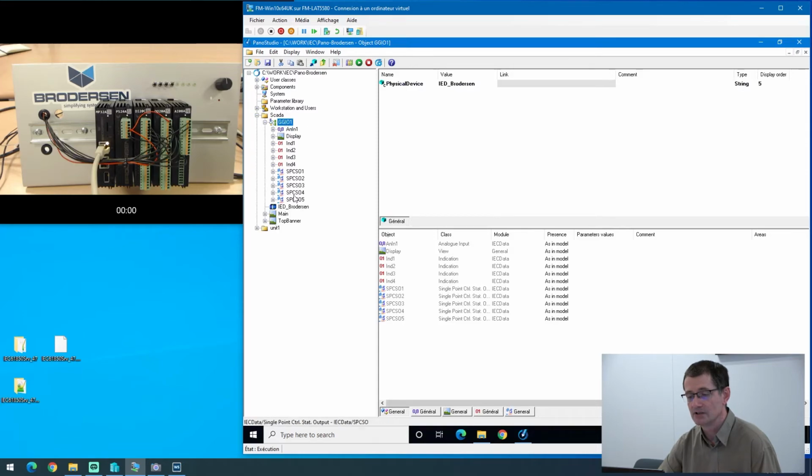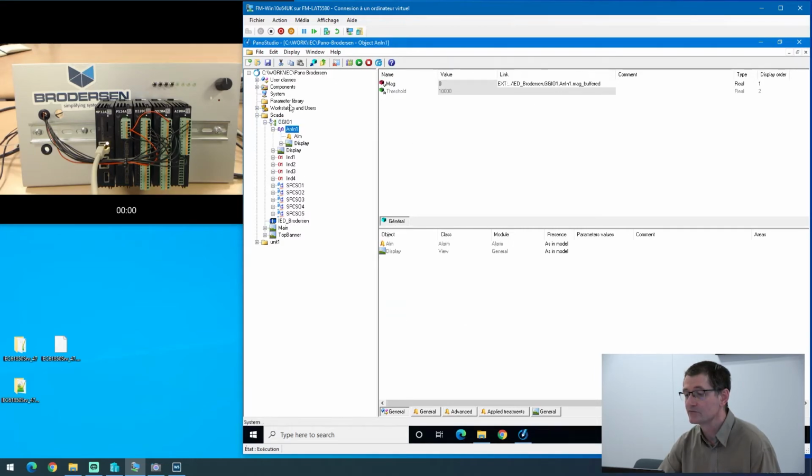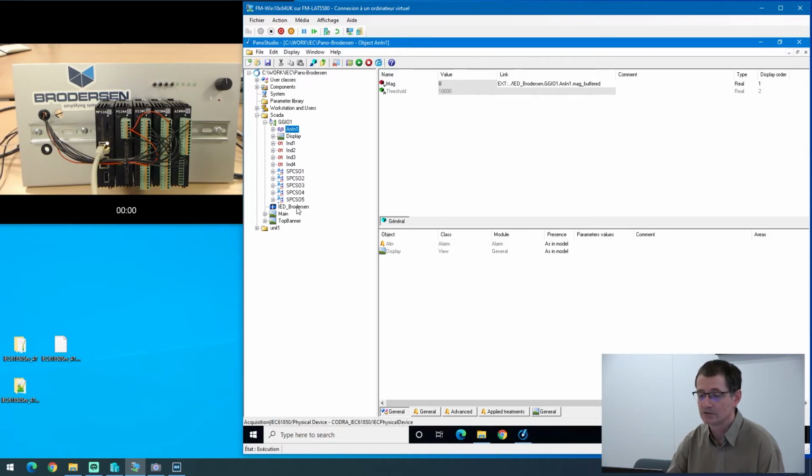And you can use this object as a source for external links, which means that you can then create components that can build the links from the structure of the components and maybe work in a more traditional way for Panorama, and especially a way where your components will already embed whatever treatment, like alarming or display, that you want to do with the information. And so here, when you work this way, it means you don't have a big connector and the component. You just have the component, and the component builds the acquisition configuration, these external links, automatically from